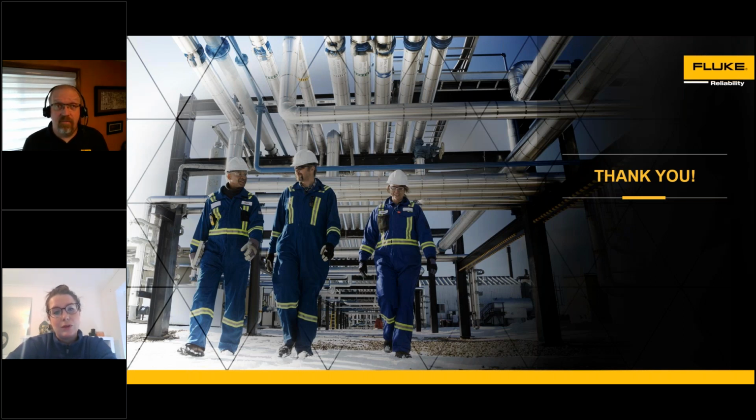And then once it's pulled out, clean up that bearing and show it to them. And have a look at it yourself first. Make sure that the fault is visible. Sometimes you may find that you've made a bearing call and the fault is a subsurface anomaly, which will result in nothing being visible, which is not great for your credibility with the maintainers. But when you do find one, and most of the time you find one that has a visible fault, show that to them. Show them what they're replacing, and have a conversation about how you're trying to replace the bearing before the bearing fails instead of replacing the shaft after the bearing fails. Kind of a roundabout answer there, but I apologize.